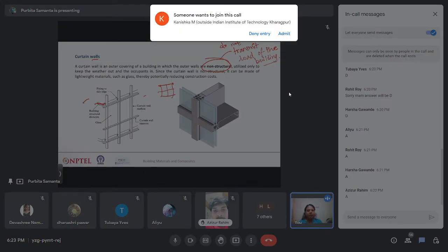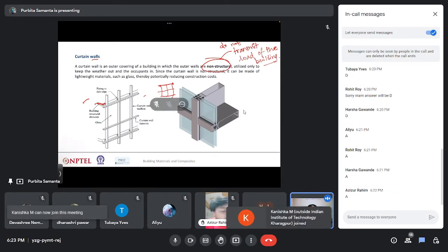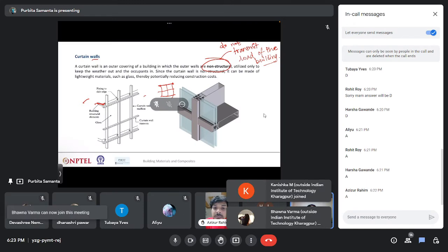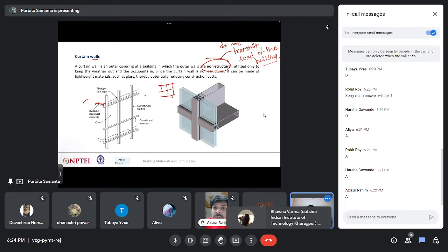So the glass that is used needs to be made of such a thing that it does not easily break. And also, these curtain walls are mostly used in high rise buildings as well. So just imagine you have a high rise building, you have designed it beautifully with these curtain walls, and then suddenly these plate glasses, which do not have much mechanical strength, just break, and you have to replace it again, and it's an entire headache, right?